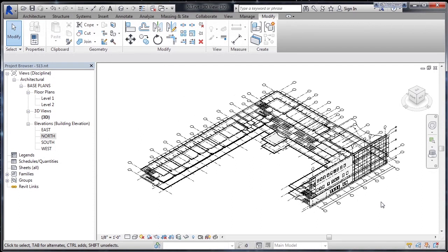So if I wanted to bring in the south elevation, I would go to the south elevation and then set the actual default plane to the other grid, in this case the letter J on the other side, and then insert in. In this case, we're linking the actual 2D CAD file to our Revit model.